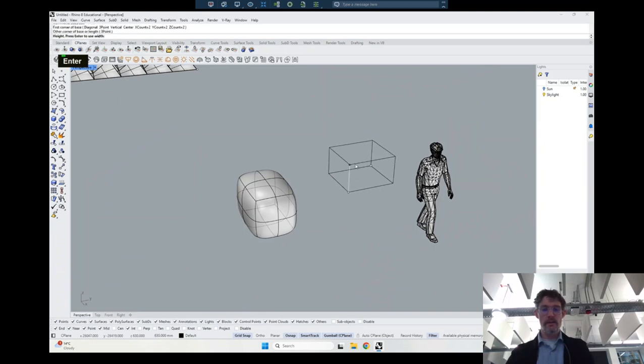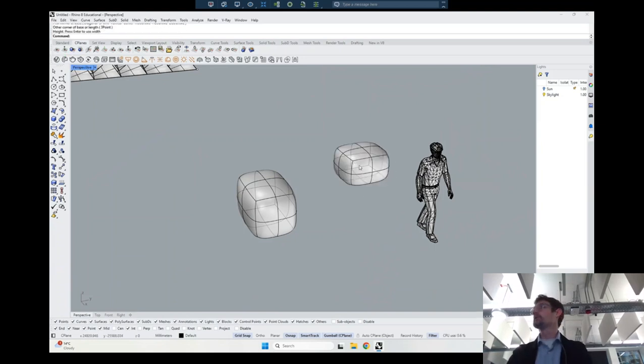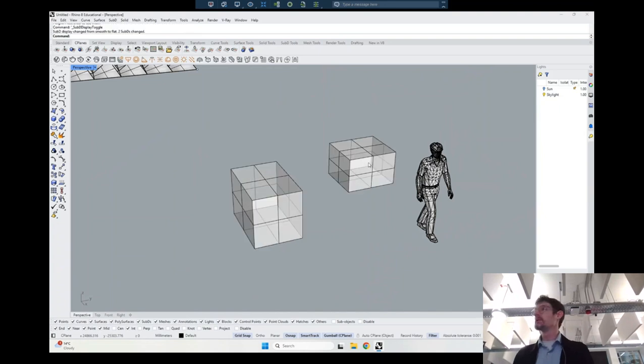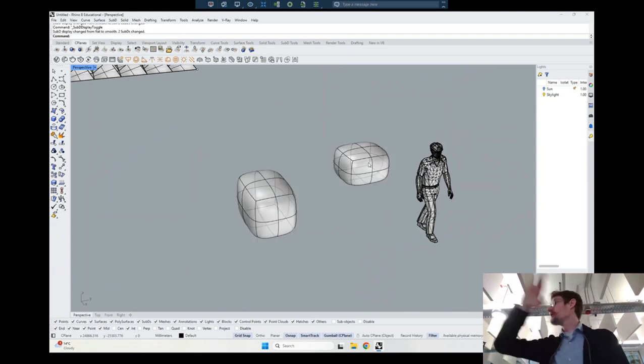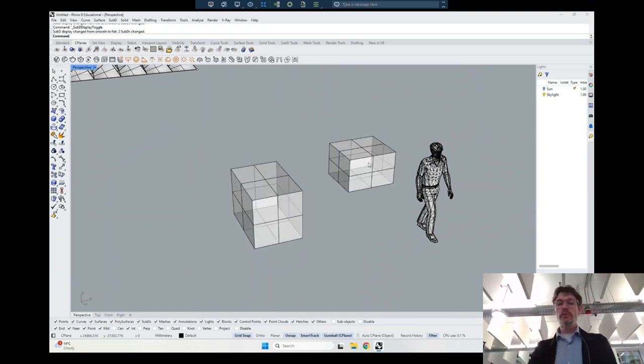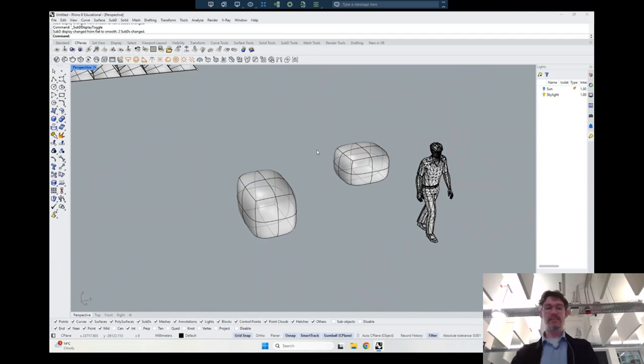I'll just start with a box. And what you'll notice is I drew a box, but what I ended up with is this weird lozenge shape. I want to see the box that I drew before it turned it into a lozenge shape. I can press the tab key on my keyboard. When I tab, I'm switching between spiky box mode and smooth sub D, 3D lozenge mode.